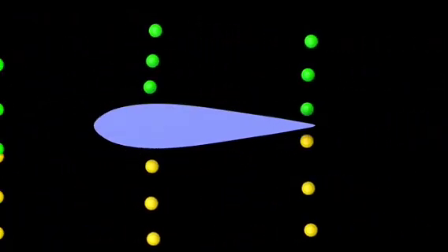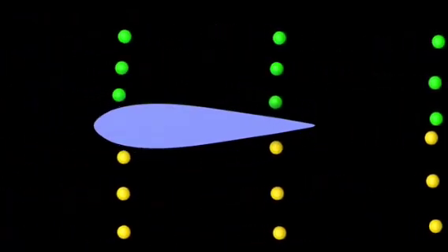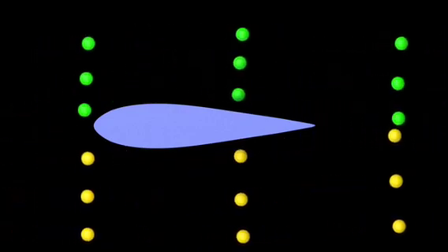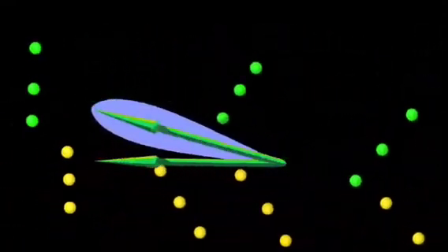Also, it is not necessary for a lifting airfoil to have the upper surface longer than the bottom. It is perfectly possible to design planes with airfoils that are symmetrical and still produce lift. For example, paper planes generate lift even though they have flat wings. This is because by keeping the symmetrical wing at an angle, we still get air flowing at relatively higher velocity on the upper surface. So angle of attack is more important than the shape of the airfoil.